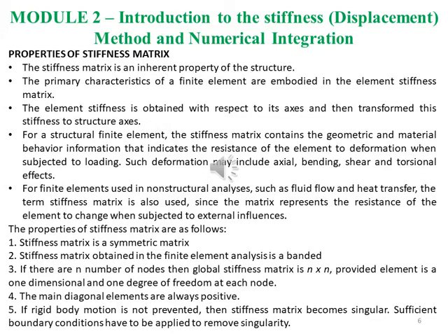For finite elements used in non-structural analysis like fluid flow, heat transfer, etc., the term stiffness matrix is also used, but there the stiffness matrix will have different properties. It will not have the modulus of elasticity as an inherent property.